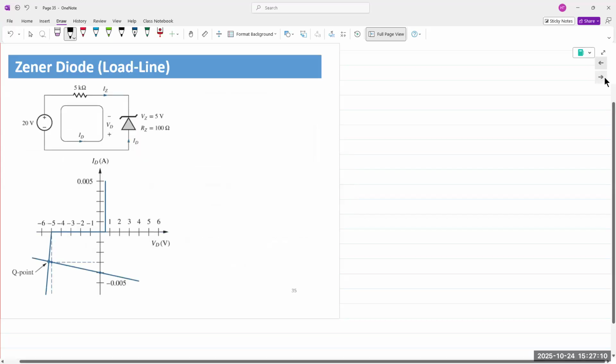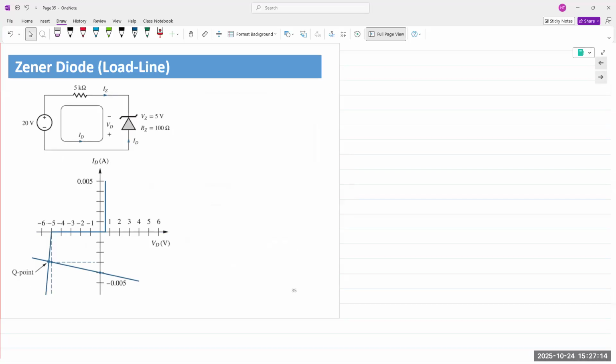All right, Zener diodes. Everybody remember Zener diode operation, how and why they work? They are heavily doped PN junctions. They are specifically formulated to operate in the reverse bias. For those of you who are in my classes, if you did sweep and go, we performed the sweep and go operation from -7 volts to +1 volt. What did you observe about the forward bias?